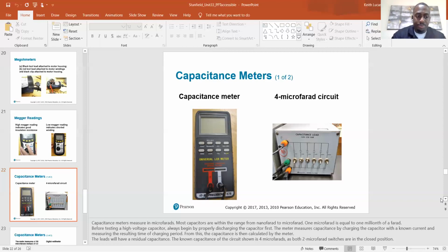And you'll put your multimeter on this function, because as you can see right here, you've got MFD for microfarads. So that's letting you know that this is the function that we're going to use to check our capacitor. So then we just take our 2 leads, put one here and one here, and then we should be getting 7.5. Oh, however, we're not going to get 7.5 because this is the bad capacitor from my other video. So right now, I'm getting 0.